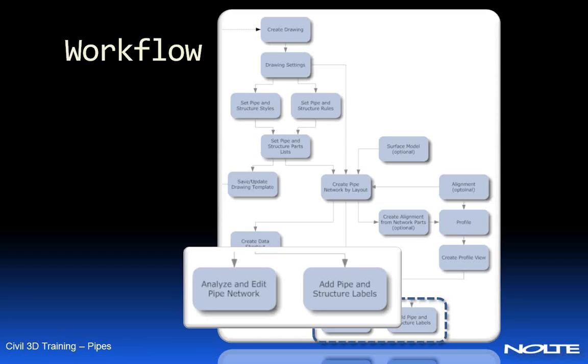On the analysis component, there are options beyond what I'm going to show today. In Civil 3D, Autodesk has provided a software package called HydroFlow, and you can actually export your pipe model directly to HydroFlow and then apply your rational method, generate inflows to all your different inlet structures, and it will then size your pipes. I can then import that back into my Civil 3D.